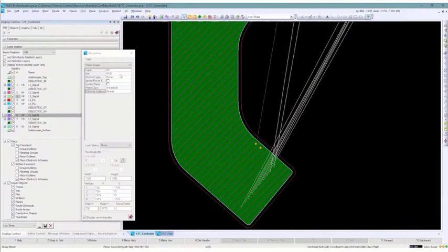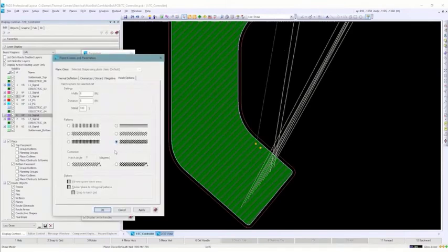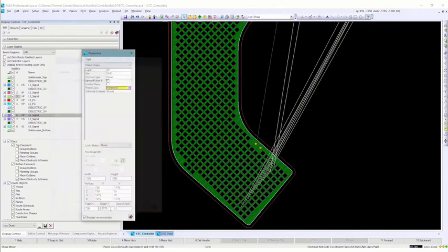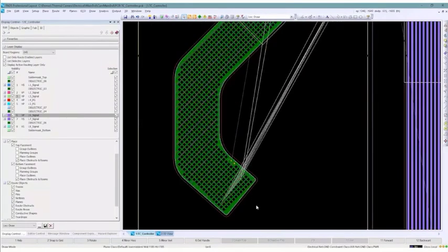All right. And you can specify any net name you want. You can click on mouse select and have it click on a net that you want it tied to. But we're going to do plane class override, which means we're going to specify that I want this to be hatched, and then I can specify a hatch parameter for it and hit apply. Now there's a couple other little parameters here, like not allowing odd angled shapes where it automatically fills them in. This can help with fabrication to some extent for acid traps and such. But you can see very quickly, I've basically created a plane area.